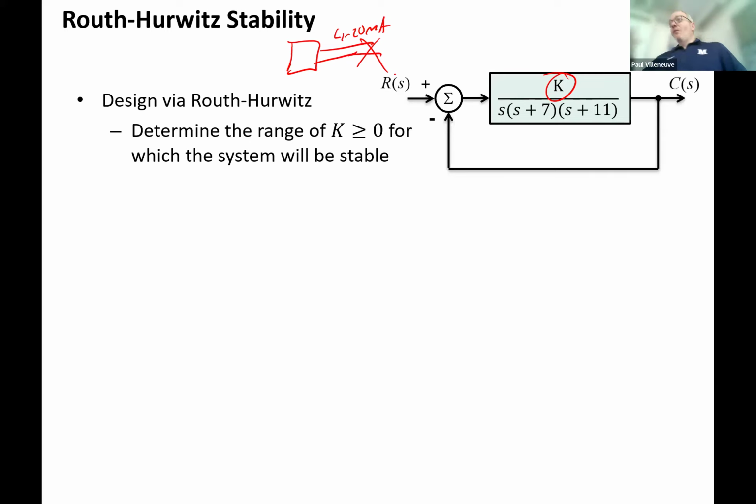That's good. So 4 to 20 milliamps is the most common. Why not go 4 to 20 amps? The biggest reason they use 4 to 20 milliamps is because if you run a lot of current, you just need bigger wires. So you can run number 16, number 18 wire, small wire, because you're only running milliamps of current. And with low current levels like that, remember what current does: it creates magnetic fields. If you have tens of thousands of wires carrying possibly 20 amps, you're getting a lot of magnetic field, and then they start to interact with each other and you can produce noise and cause issues.